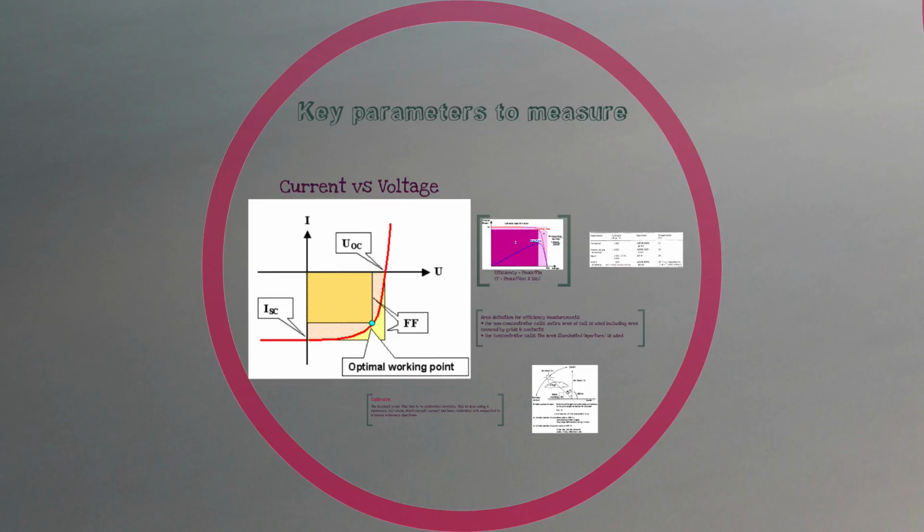So you have a reverse bias PN junction. You shine light on it. Carriers are created. Current flows, which means that the current flow is essentially opposite to the applied bias. So you always treat this as a curve which looks like this. If you do it in a conventional sense, current is negative as you apply the bias. This is reverse bias, and you will see a curve which looks like this.